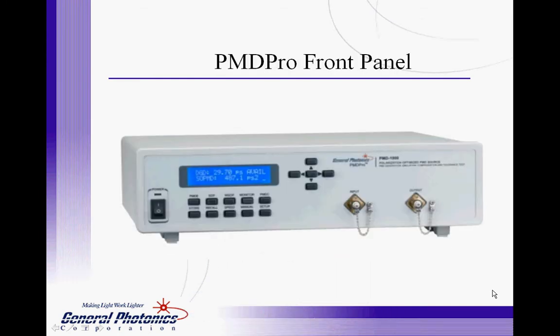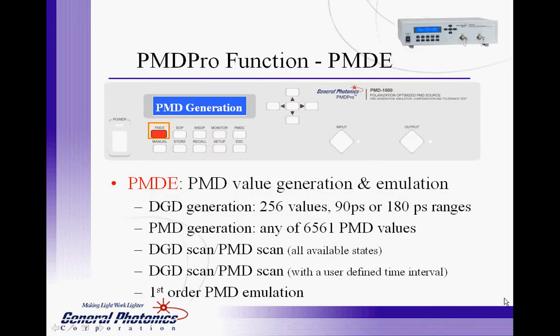PMDPro provides a very user-friendly front panel operation. Let me walk you through three typical operation modes. Pressing the PMD key accesses PMD generation functions, including generation of a single DGD, or PMD value. Scanning through all available DGD or PMD states. Scanning through a user-generated sequence of states. Or generation of a Maxwellian distribution of DGD states.